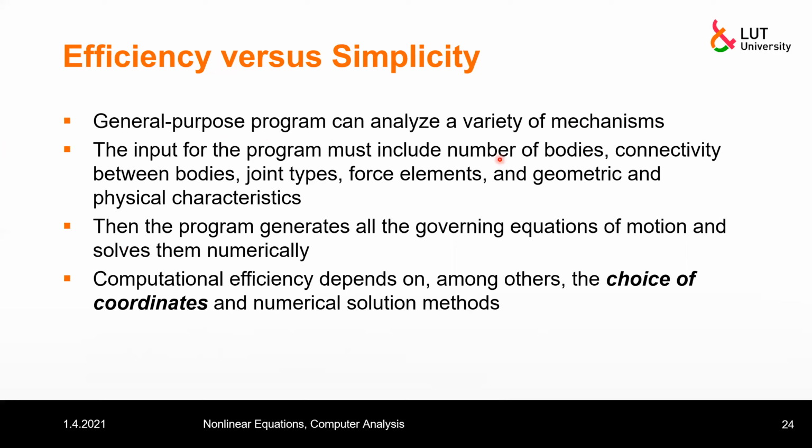So that's why we need some bodies, connectivity between bodies, joint types, forces, and some other properties like inertia, geometric properties, and some others. Then all the equations must be generated by the software, and the software must also contain a solver that will solve it numerically and provide readable information for us.